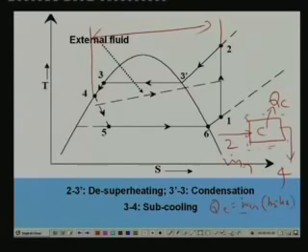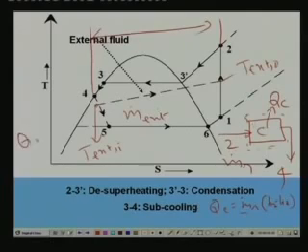Okay. And from the external fluid side, let us say that this temperature of the external fluid is T external in, and this temperature is T external out, and let the flow rate of the external fluid be m dot external. Then QC is also equal to m dot external into Cp, some average Cp of the external fluid, into T external out minus T external in.